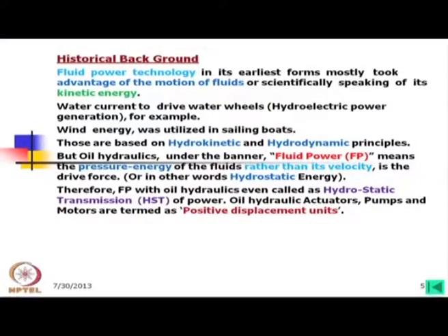If we think of the turbine, there the fluids with potential energy converted into kinetic energy, and that transmit the power to the impeller of the turbine, and the turbine rotates. Whereas, in case of fluid power, we supply the pressurized oil inside the actuator and it moves, like when it is giving the thrust to the piston, it is like a solid bar generating a thrust on it. Alternatively, if we use the rotary elements, the same pressurized oil is working, and that is why it is called hydrostatic.